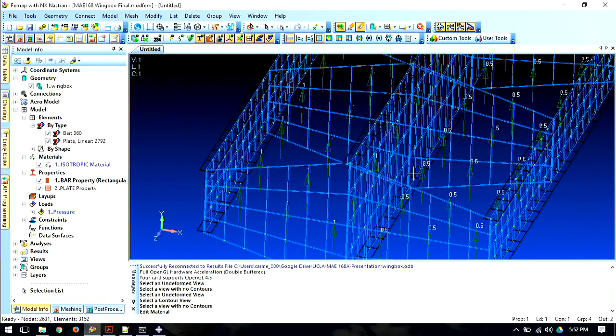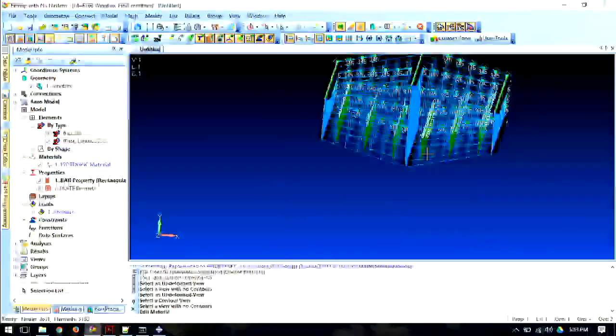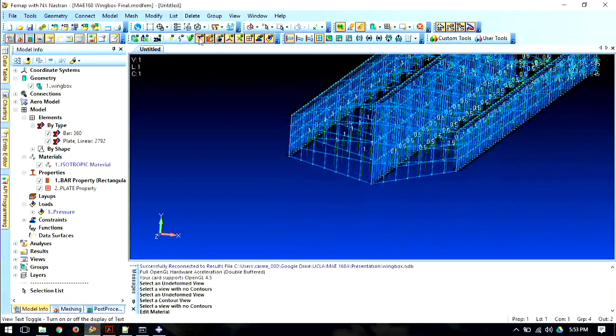I think in the slides it had 2.5 by 1.5, but I don't follow. What is that? This is the pressure loading on top. Okay. So you do that different to have closure? I made it different so that I can do some kind of torsion. And it follows generally where the center of pressure is for a wing. It's about a quarter of the way, 25% in front of the leading edge. Typically, it moves to the center if you're going above Mach 1, but I'm not going to go into that.